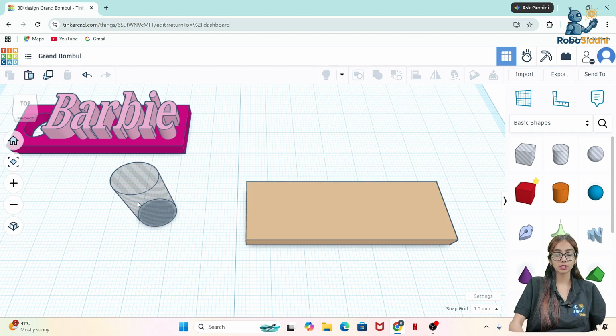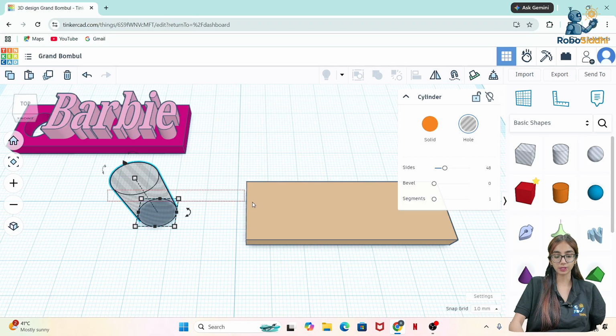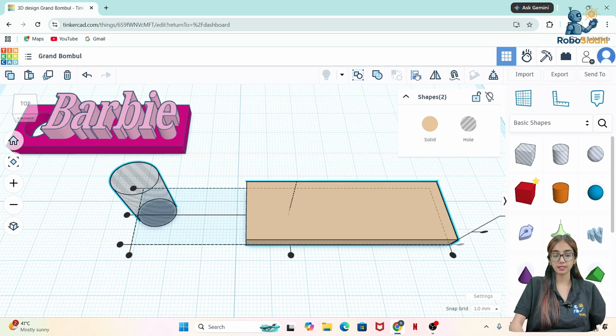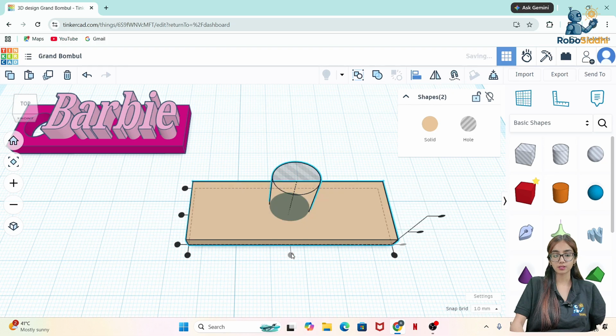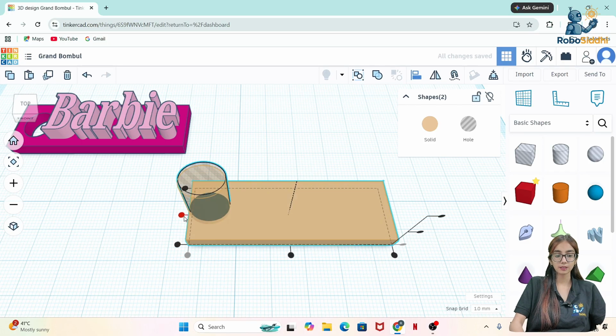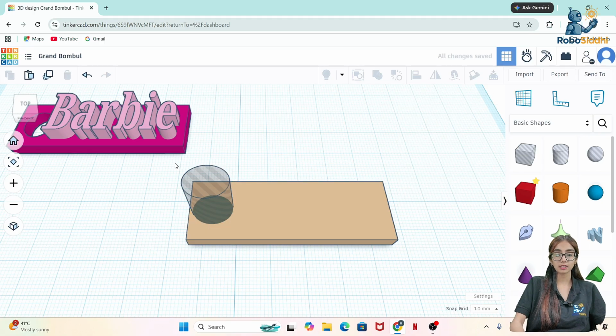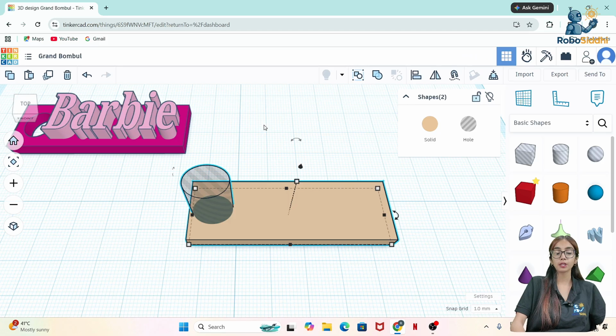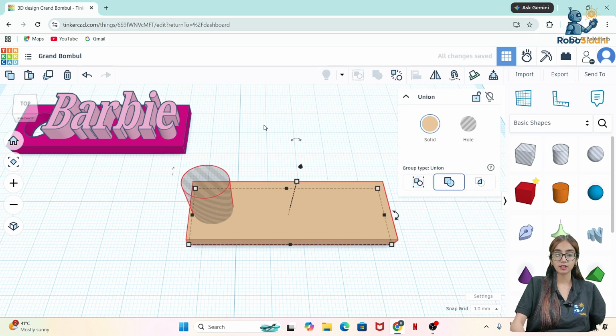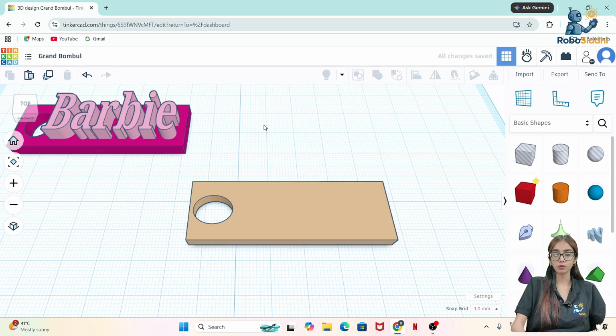So right now, what do we need to do? I'll just simply align both of them. Okay. So I'll align them like this, and I'll watch where it is placed. I don't need it in the center because I need to fix my basketball or football over here, right? So I'll just fix it on this side. I can always change my hole's location. Okay. So now the next step is to group them. For grouping, I need to select Control plus G, and I'm getting a hollow space again for the key holder to hold.